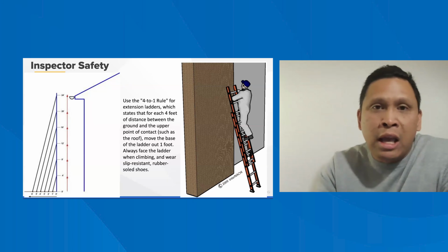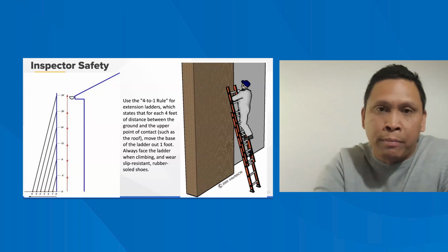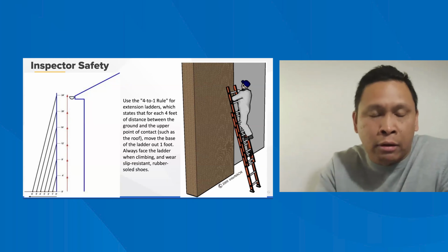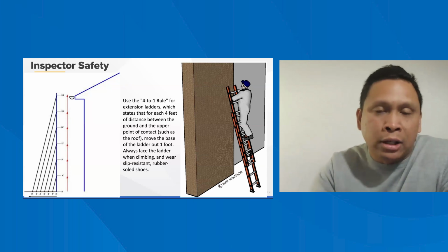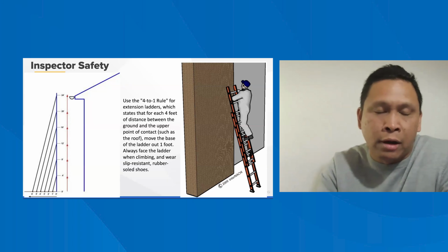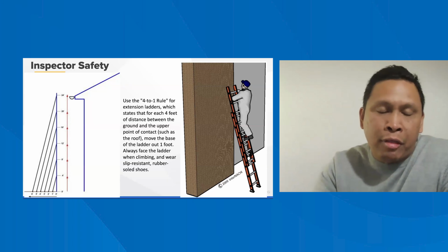So if for some reason you heard a buzzing system, since we're talking about safety, I'm going to digress a little bit from the actual structure, but I think it's important. If you heard a consistent buzzing noise on an electrical panel, naturally you're not touching that electrical panel, and for safety reasons you're going to put an inspection restriction on the report itself.